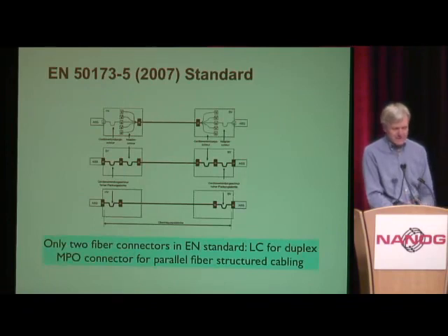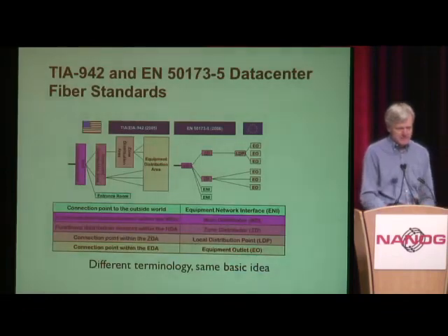And they actually made it into the data center cabling standard in Europe, known as EN 50173-5, which lists both the LC connector, which is the duplex connector for the equipment termination, and then the MPO for the parallel fiber structured cabling between the racks, which is what most people do. And there's the equivalent in the TIA standards. They use different verbiage, but it's essentially the same concept.